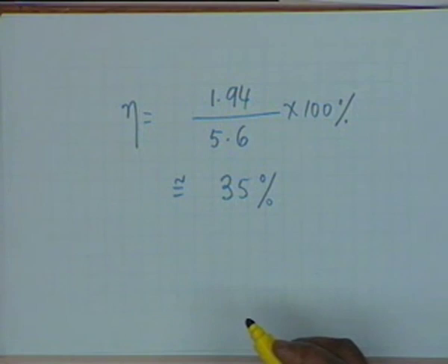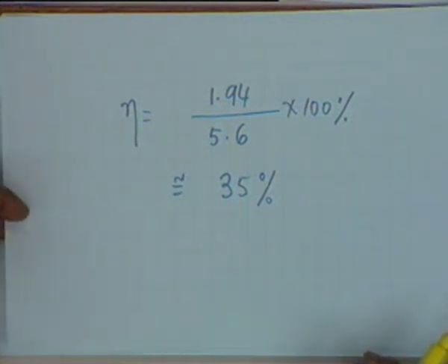The theoretical maximum is 50, what we can achieve is approximately 35%, and this is a fact of life. All right. The design has to be very carefully done by looking at the transistor characteristics. For power amplifiers, transistor characteristics are a must if you wish to keep the distortion to within reasonable limits.